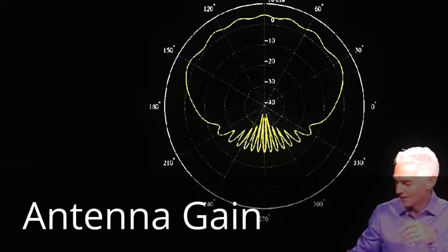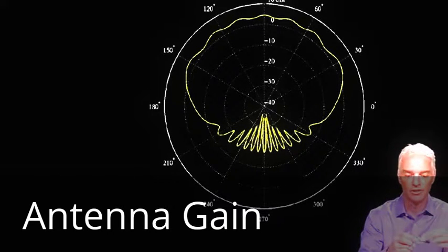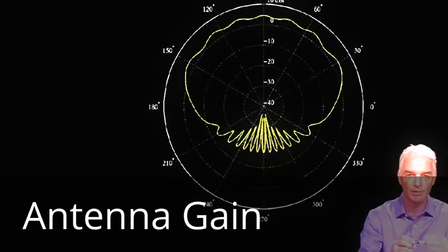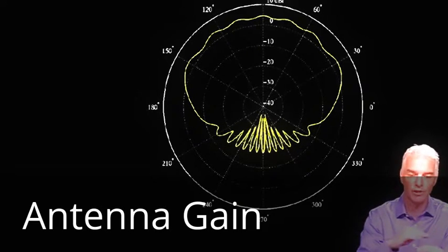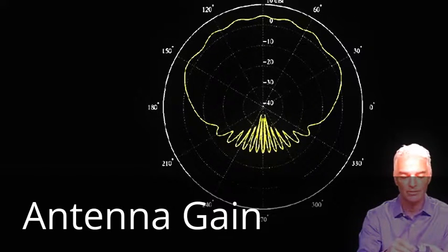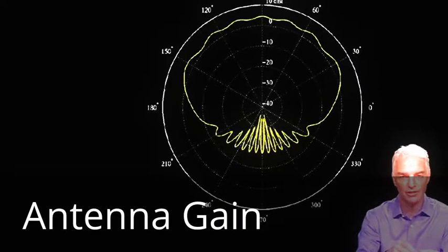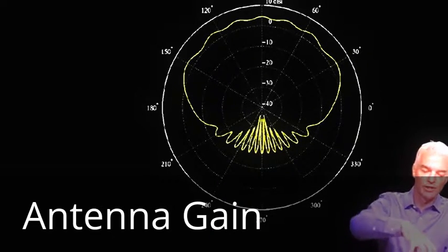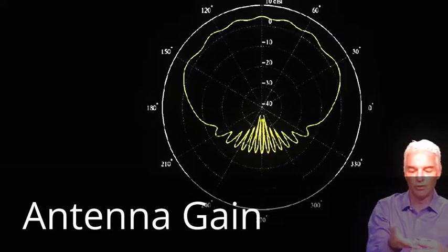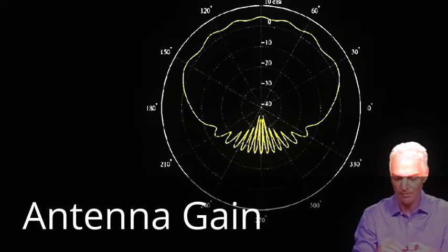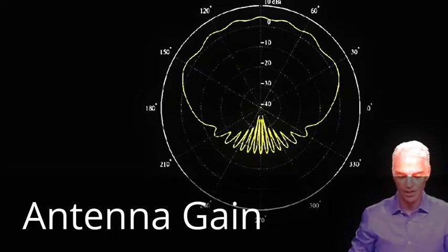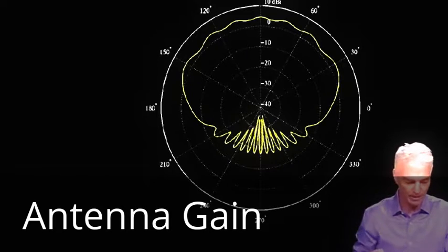And inside of that, you would see this. There's literally a patch and a small ground plane. And if it's part of a car, then you'd have a large ground plane. And because of this construction, if this antenna transmitted a signal, all the energy goes up in a hemisphere and almost no energy goes down because of that ground plane. And that's what this gain pattern shows us.